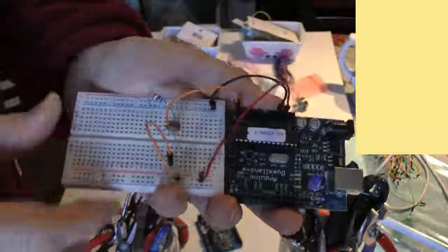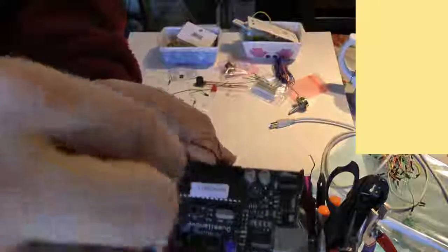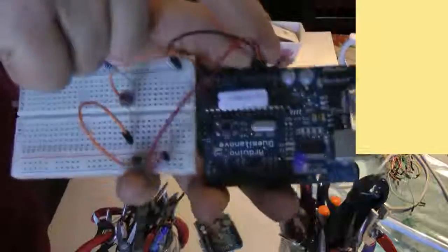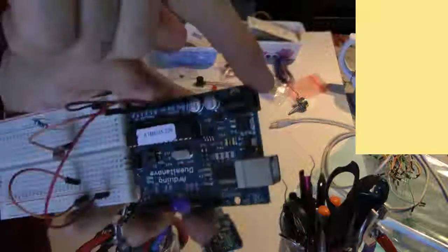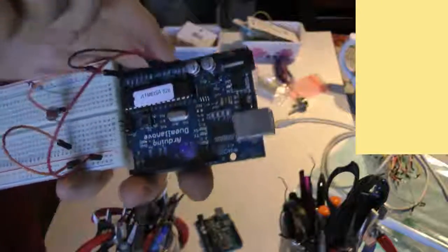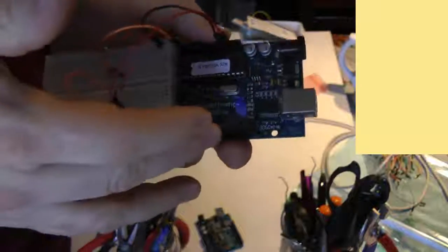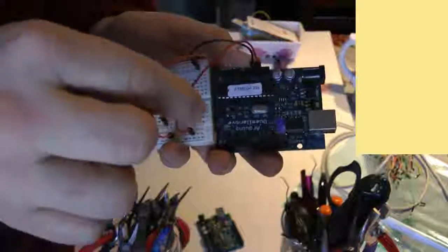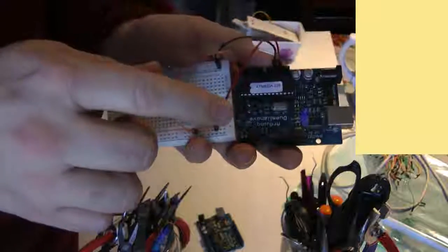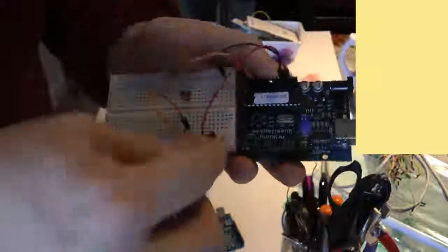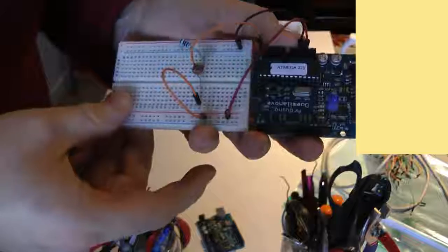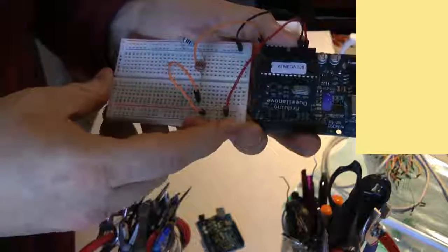Now what we have is this red wire running from the 5-volt positive, because this board is giving us, it's got a regulator on there, and if we had a 9-volt plugged in here, we'd still be getting 5 volts out of this. So these boards are handy for developing, which is another reason I recommend you start with these. So basically we took 5 volts here and brought it over to our proto board.